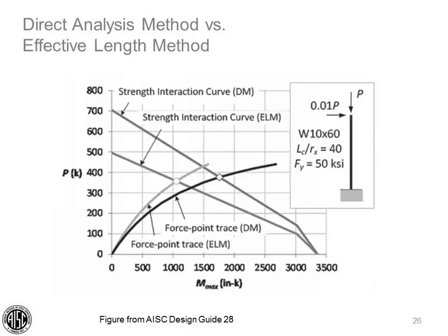In the previous cantilevered column example, I used the older pre-2010 effective length method without notional loads to highlight the difference between the two methods. The current effective length method does require the application of notional loads as a minimum lateral load to be applied in combination with the gravity loads. However, even with the application of lateral loads, the effective length method still underpredicts the moments, similar to the previous example, as can be seen here in this graph.